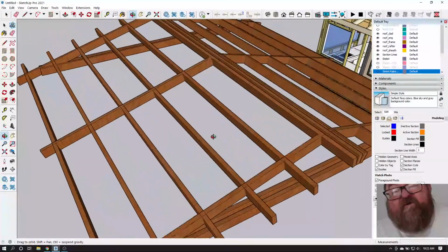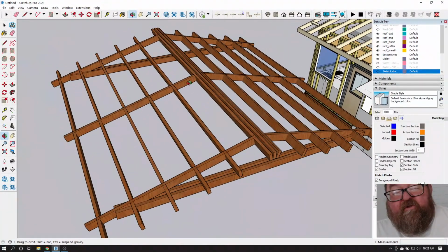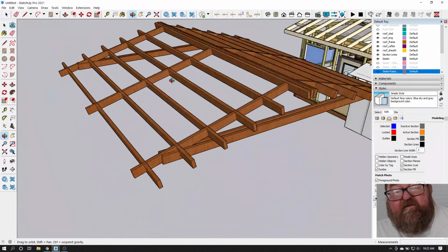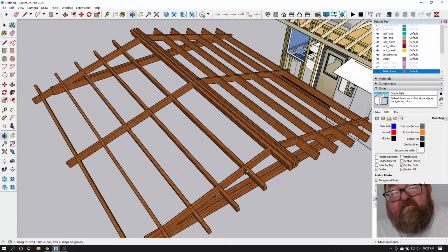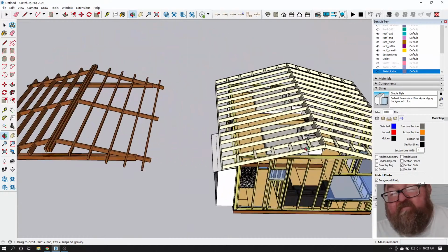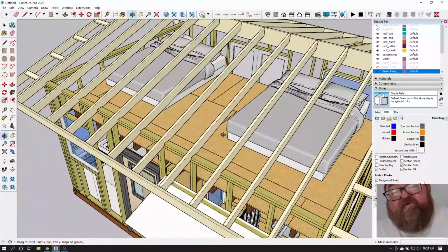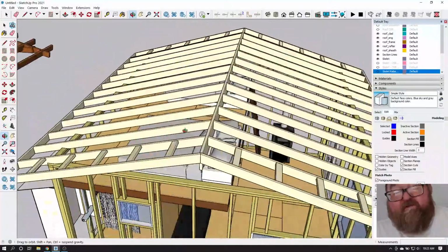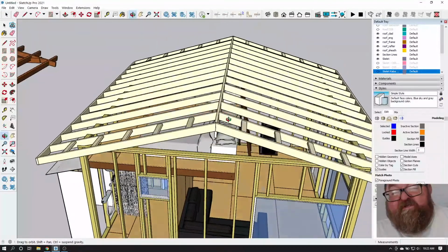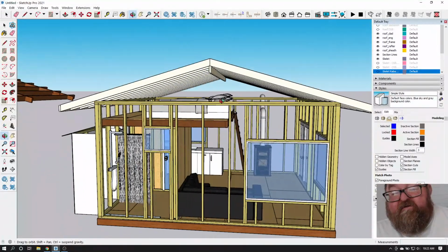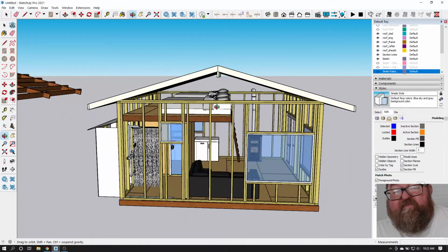If I ask you what is supporting the roof, what are you going to point to? Are you going to point to this thing, or to these? What I'm pointing to is my rafters. Now let's answer this issue of ceiling joists and collar ties. We don't have anything right now keeping this building together.